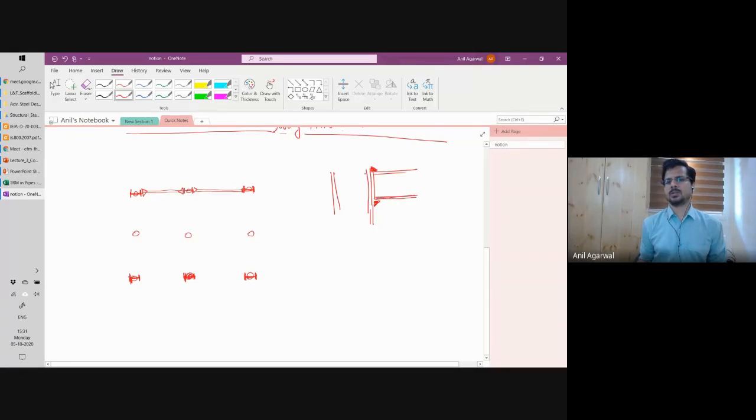If I have some doubts about the rigidity, I can put some stiffeners here. Okay, and that will give me enough rigidity. Or if I have any additional doubts, I can also put another stiffener here in the column. So that is typical detailing of a rigid beam-to-column connection. But if my column was, so this column from the top will look like this.